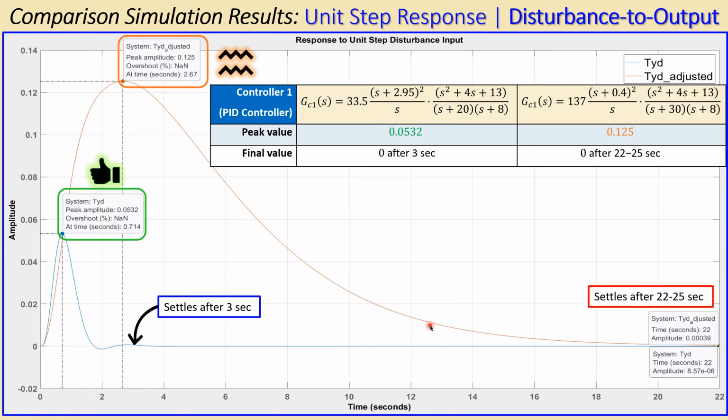All right, so we now have the complete picture, and the only parameter we haven't managed to get is the disturbance, and that is another trial and error cycle. But I was already happy that I had managed, by tuning 3 parameters, to get the overshoot and settling time done. The disturbance peak is not really that high, but it is higher, and the tail is much longer. So there is something we can also win by adjusting a parameter here.